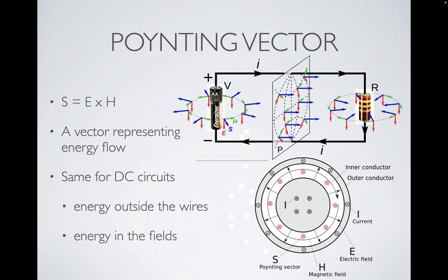So you have a magnetic field formed by the wire with current in it, and you have an electric field because of the voltage differentials. And if you do the calculations with E cross H, you'll find out that all of that energy can be accounted for in the fields, which means that it's not really flowing in the wires, which is a pretty interesting concept. And this works at RF as well, but at DC, you have a Poynting vector, and that's how it does work on things.